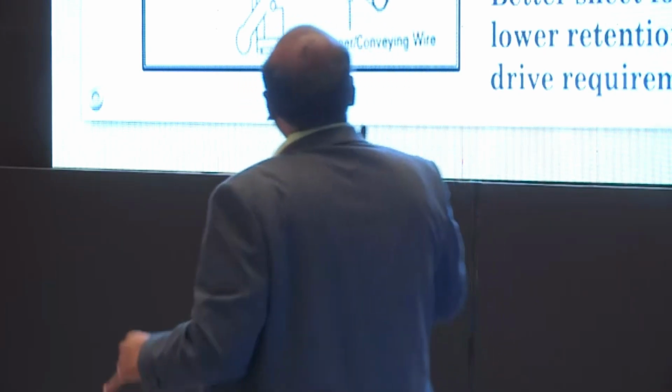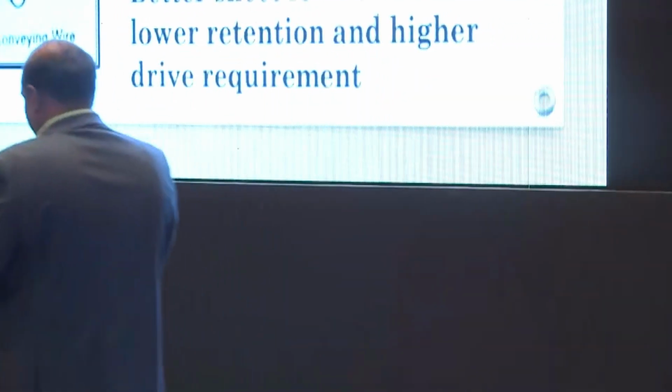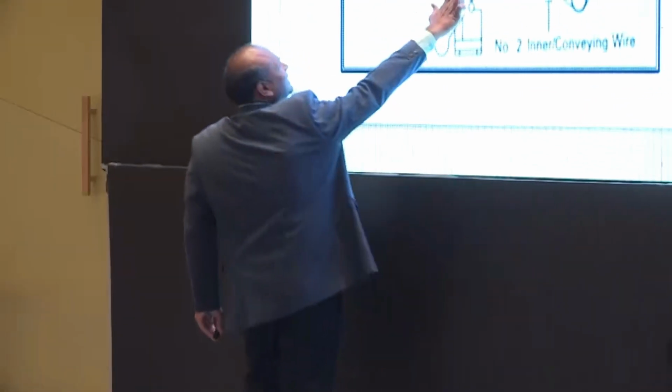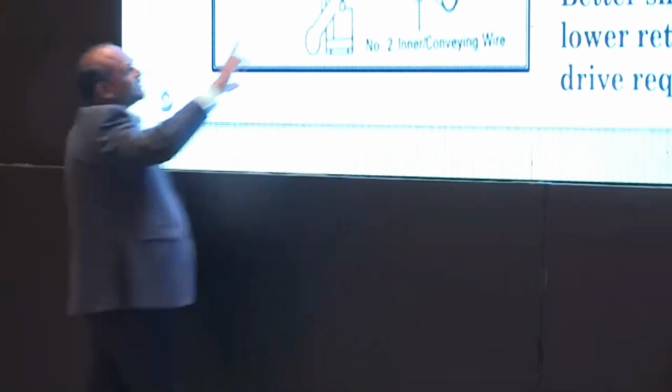In that, the first category is blade formers. You can see this is the head box, and the converging wire, the pulp jet is going inside, and both sides we have blades. It's similar to our Gillette razors. You can see that 3 or 4 blades will be there to make it smoother. Similarly, on both sides of the wire they used ceramic blades, so that with increasing tension and pressure, the water will squeeze out in both directions, and immediately at the top of the couch roll you will get the desired dryness quicker than the fourdrinier.